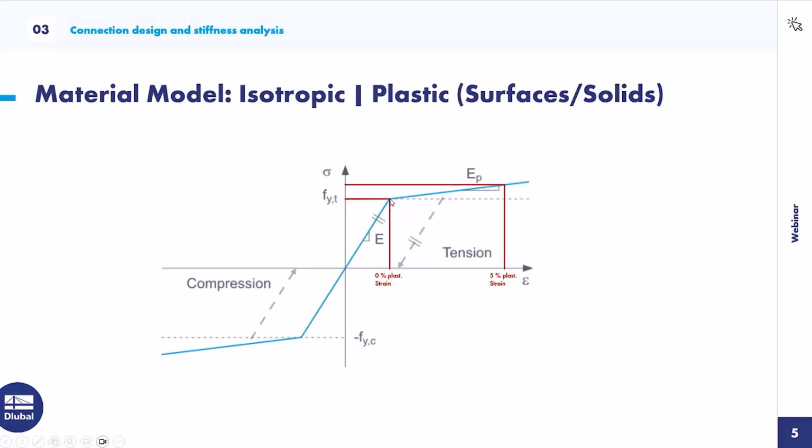That means you can't increase the load with a factor 5 or so. That's not possible, because that's the area of the plastic strain, but we have already got an elastic stress and elastic strain in the model.